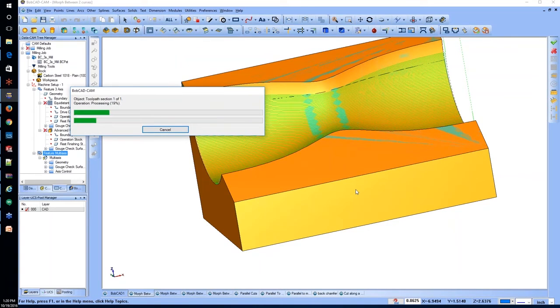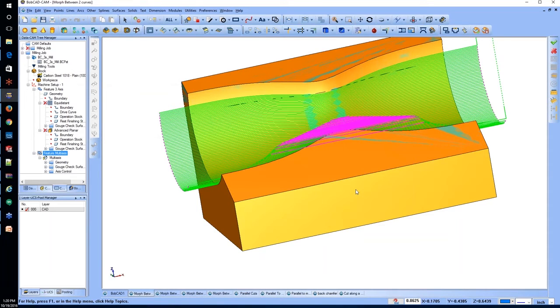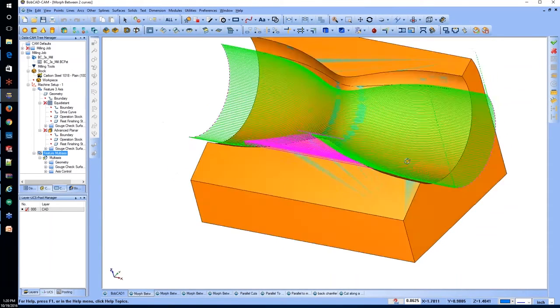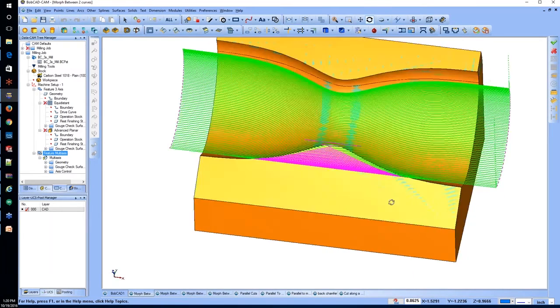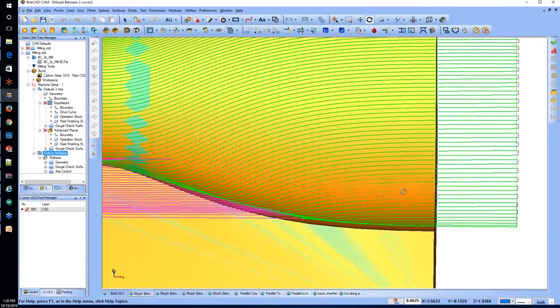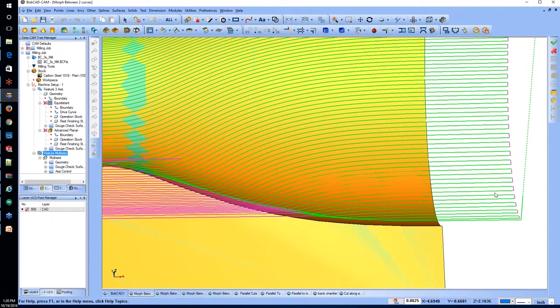What it's going to do is extend the tool path out following the surface without me having to do any extra moves. Boom. See? So we extended, and this extended these ones here, so it still has to wrap it because these are the next parts, but that's actually extending the start and the ends of the tool path as it comes across the contour. But there you go. There's your extend and trim. As easy as that, you guys can output your actual extend options.